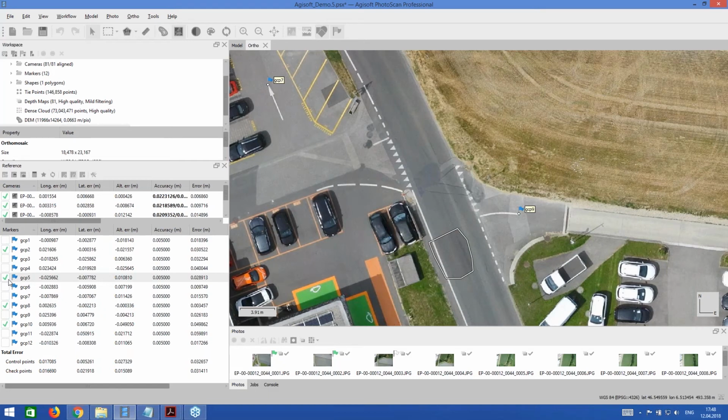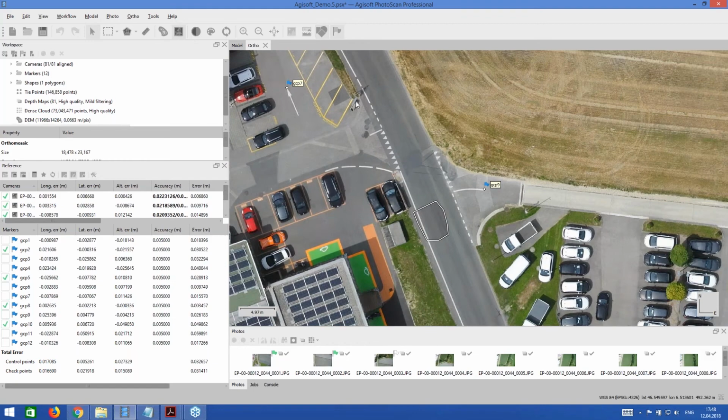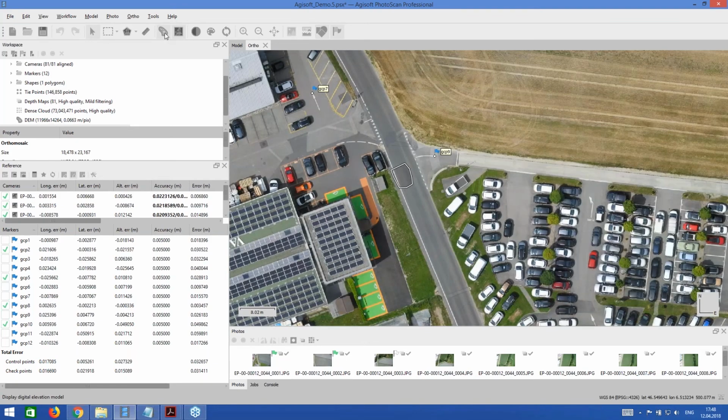So in principle, it is possible to get comparable results with ground control points, but not in every project are you able to take a sufficient number of ground control points, and that's why the RTK system is now getting popular, so you don't spend time and resources gathering a set of ground control points like 10 or 20. You can use only a couple, maybe 3 points for accuracy validation, just to confirm that the result fits the accuracy requirements of the project.